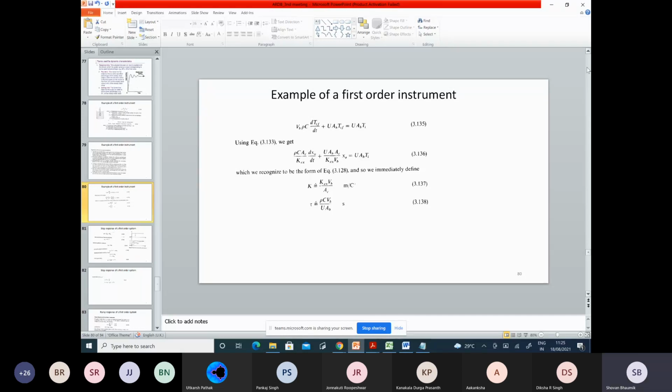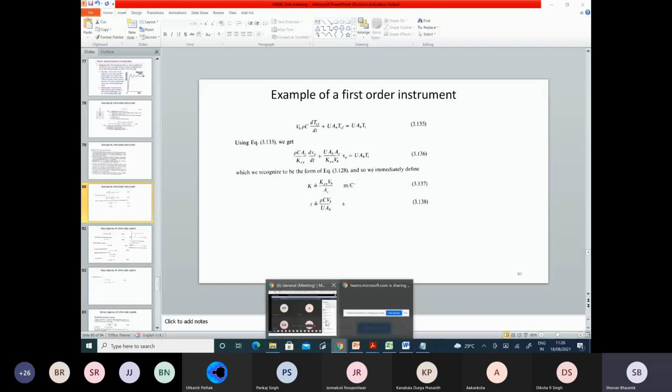By selecting different parameters, such as the volume of the bulb, the liquid inside the bulb, the specific heat of the liquid, the surface area and volume of the bulb, and the capillary length, if we choose properly, we can have a sensitive and more responsive instrument. In such a way, you should design an instrument. Okay, so if there is no query, let's move to the next part.